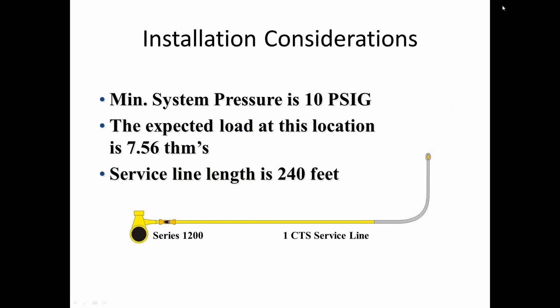This is where there are some things that have come up in our past history with excess flow valves that I think are important to keep in mind and consider. Early on, as excess flow valves were becoming more and more used, some of the early issues on installation were calls where the EFV appeared to trip, and the customer didn't necessarily want it to trip, and it would happen during the blow off of the service.